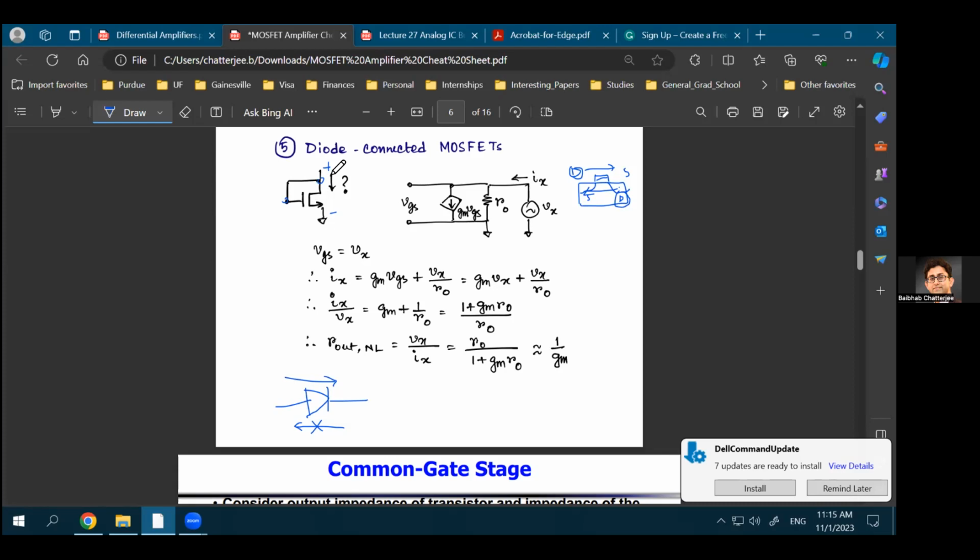That's an absolute truth; you cannot reverse that. So if for the NMOS the current flows from drain to source, then you know that the drain terminal will always be at a higher potential than the source. Okay. So this is how we are defining the drain, and then we are connecting the drain